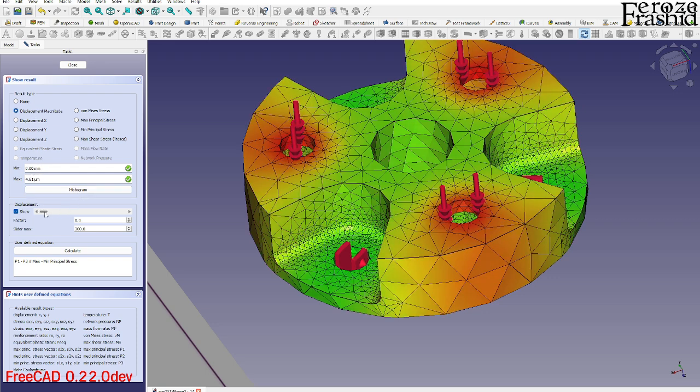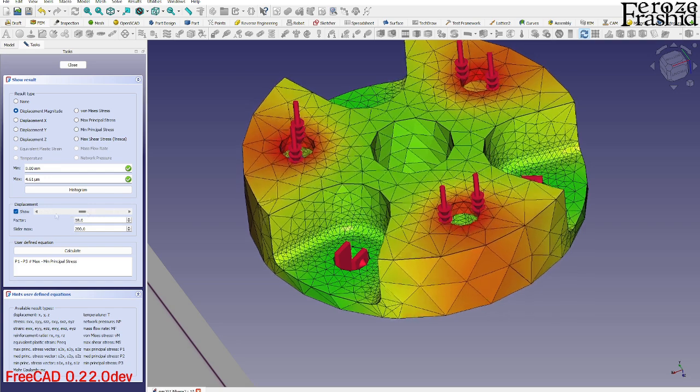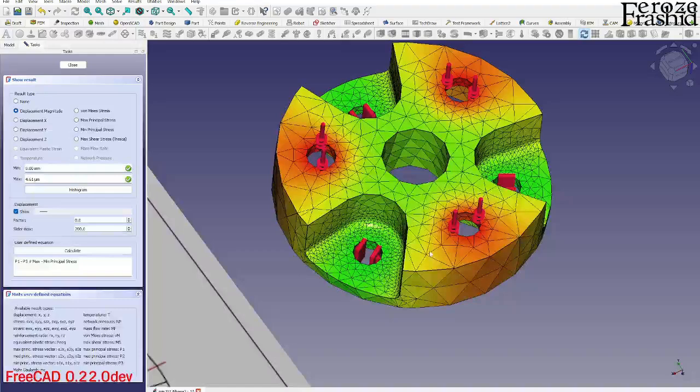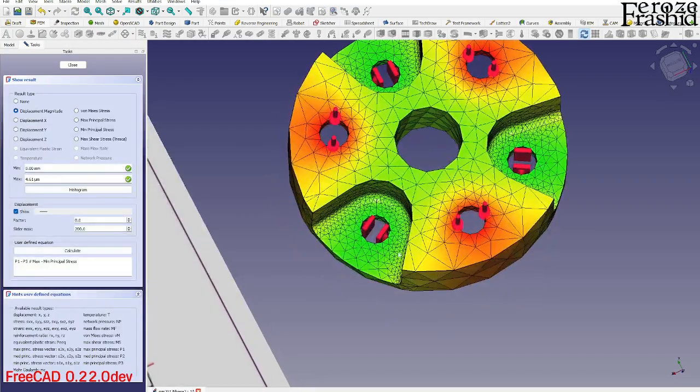Now if you are using this in a machine where deformation is a big deal, that matters. But if it is something to hang on the wall, say you're fixing these 3 points on a wall and then hooking something up just to hang things on it, I don't think deformation is a big deal. In that case it would be the stress, so you would look at the stress.